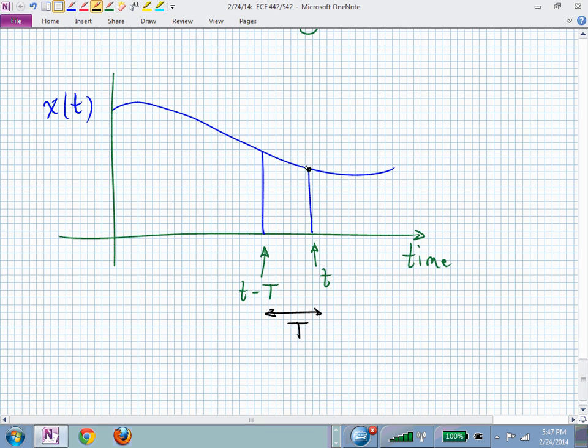This point right there is x of t, which we are actually going to go ahead and say t is little nt. Let me then erase that and say this is now going to be x of nt, since that's where we're going to just say, oh, this t is now at the sample period n, capital T sample periods into time.